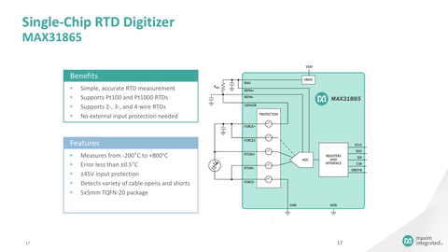This device is fairly accurate, having an error of less than 0.5 degrees C. And under most conditions, it typically performs better than that. RTDs are frequently used in factory environments where the sensor is connected to the measurement circuitry with long cables, which can get shorted to a power supply voltage. This device incorporates protection against an overvoltage between plus and minus 45 volts on the inputs, which might destroy a measuring circuit based on a typical low voltage ADC where this type of protection has not been included.